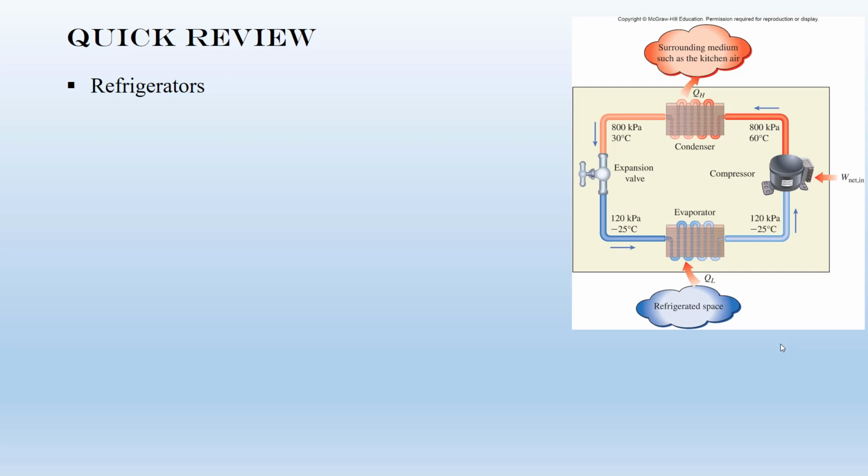If you remember, normally heat is transferred from a medium with higher temperature to the lower temperature. If you want to transfer heat from places with lower temperature to the higher one, we need to use a refrigeration cycle. For the refrigerators, normally we have four different steps. The first step, heat is absorbed from a refrigerated space, or from the heat sink. And then there is an evaporator. In this evaporator, the working fluid, at constant temperature and pressure, converts to saturated vapor.